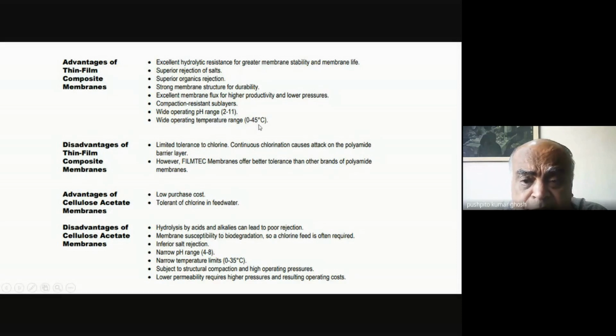This is important because the reverse osmosis flux has been found to increase with temperature. Even though the osmotic pressure goes up with higher temperature, the effect of temperature in terms of reducing frictional losses is greater, so you sometimes may actually want to operate at a higher temperature.